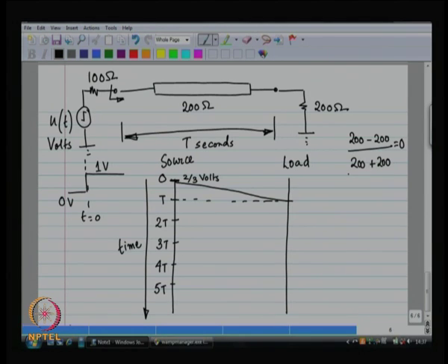Fantastic. So, nothing reflects back from the load, the entire voltage waveform is absorbed, and if nothing reflects back, we do not have to worry about subsequent reflections. The load looks like a black object, whatever you transmit it absorbs.